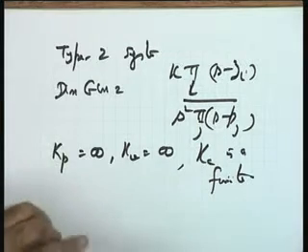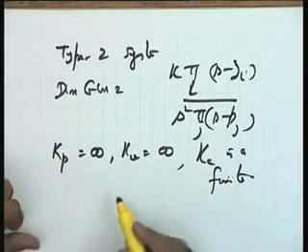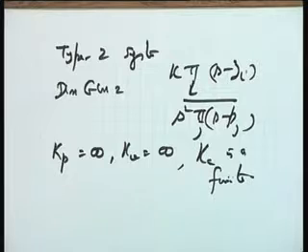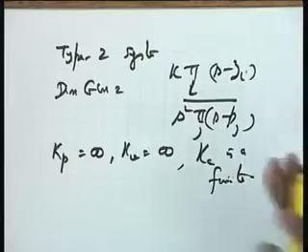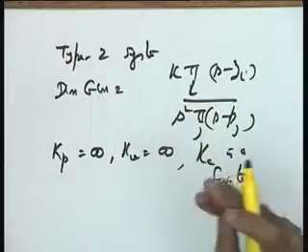Is it okay, please? Can only a D control decrease the type number of a system? Only a D control, yes, a question please. A D control only, if you take it in the forward path, again it is a question of where the cancellation comes. So if it is a type 0 system, it does not, otherwise it will, mathematically speaking, yes.